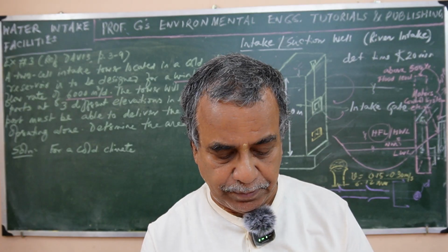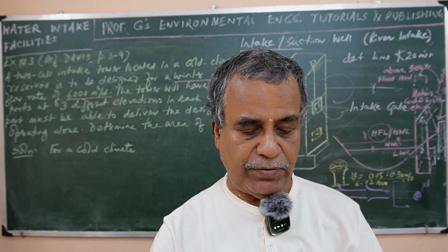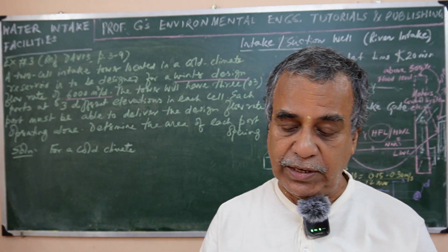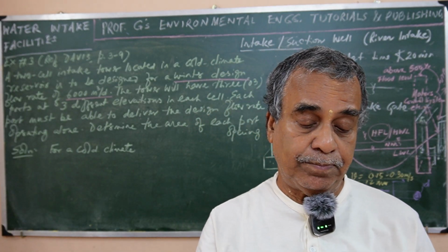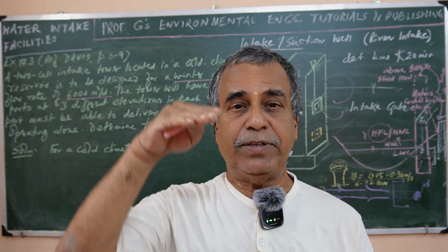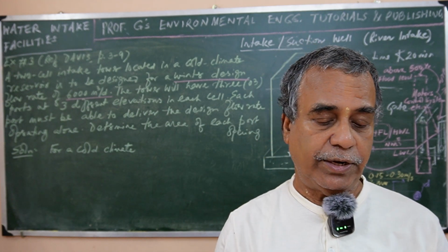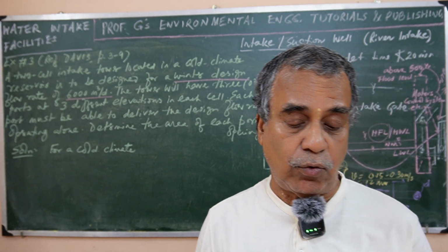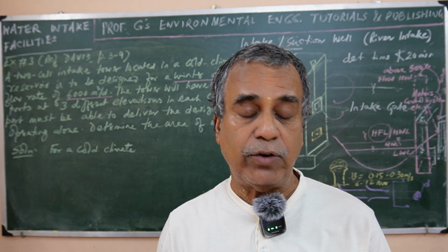For example, I will just read from this Davis book: intake ports at various depths to allow for changes in water elevation. Please note that ports at different depths have to be provided, to allow for changes in water elevations and changes in water quality due to wind and wave actions.